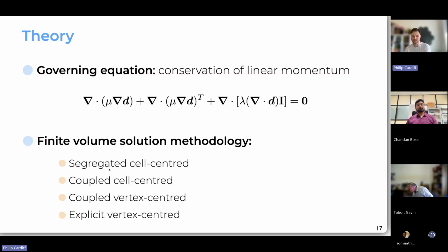You can use the standard OpenFOAM approach, which is a segregated cell-centered solver. But also more recently, I've been working on coupled or block-coupled implementations as well, both cell-centered and vertex-centered. But also you can look at fully explicit solvers. So there are various different ways to solve this equation that have different merits.